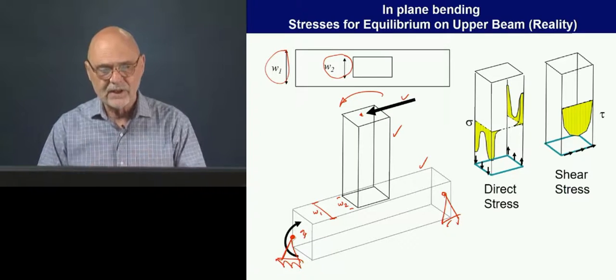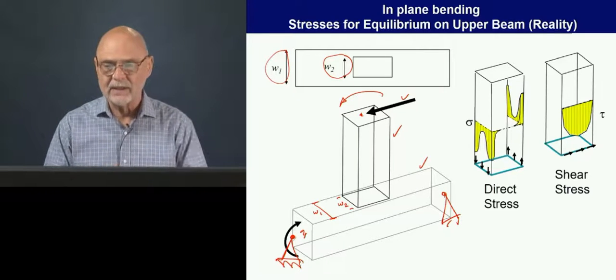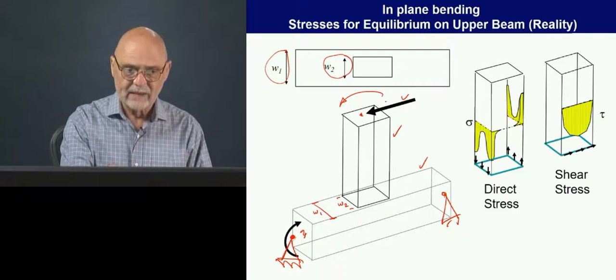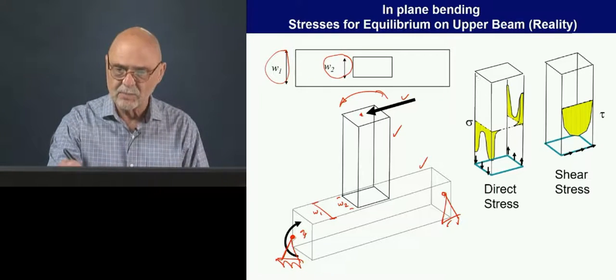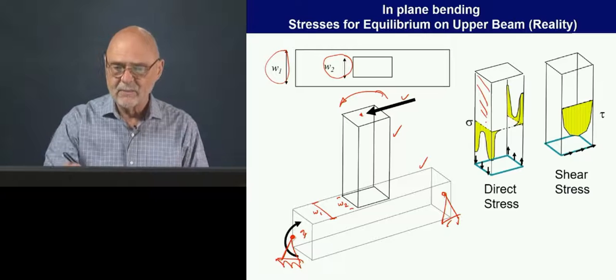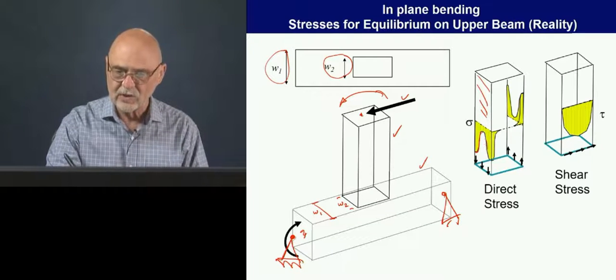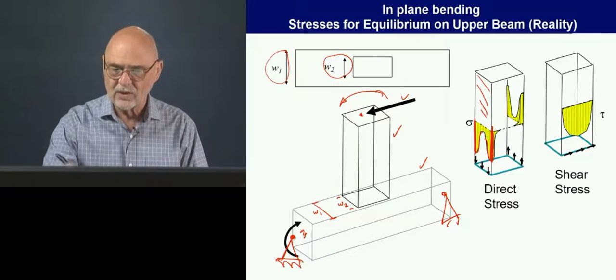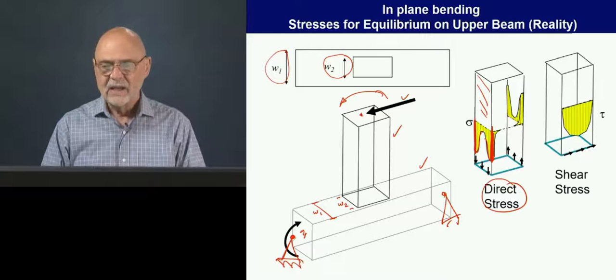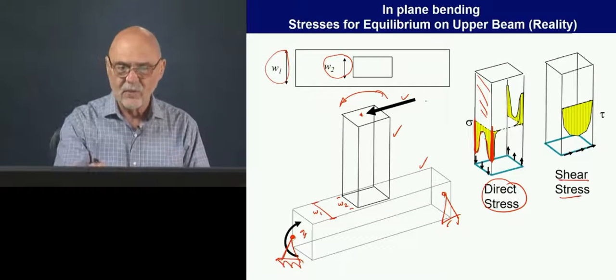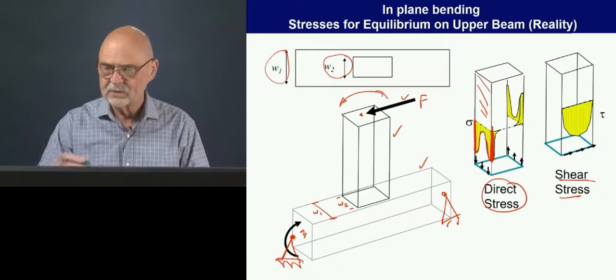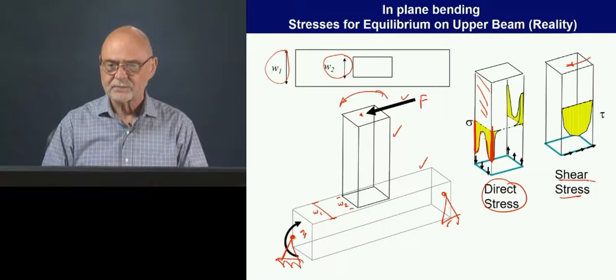And we know from our studies earlier about plate buckling that for thin wall structures, when we apply a force or a moment, here's a plate here, most of the loading will occur at the corners. We'll have not only the corner loading here from the direct stress, but in the case of a force, we'll have some shearing stress that we need to generate here.